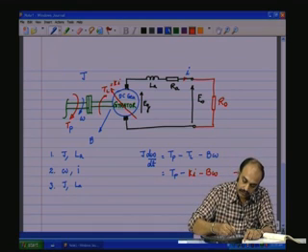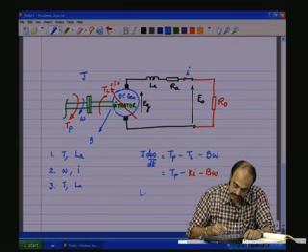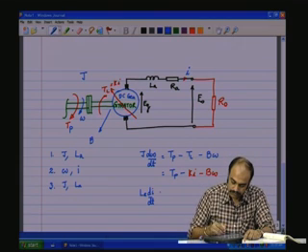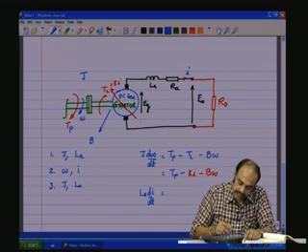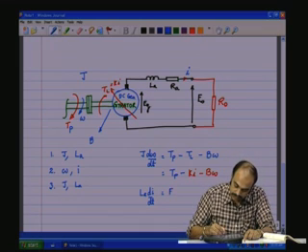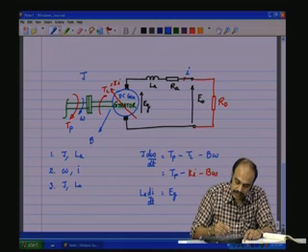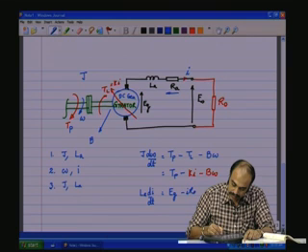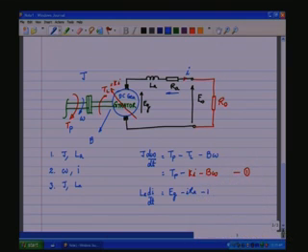Now, the second equation is on the electrical domain side. Again, that is also inductive. LA into d by dt of the flow variable, or the kinetic variable, which is i, is equal to the generated EMF, Eg, minus the drop across RA, minus the load voltage, but we have to express everything in terms of input or state variables.